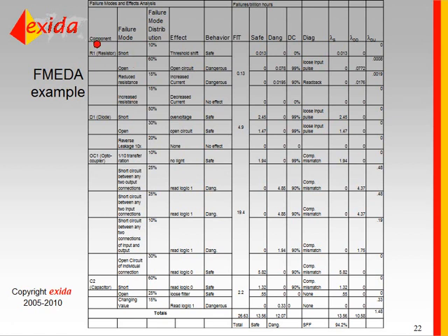So we can look at this resistor, and we know for whatever type of resistor this is that there's 4 failure modes. It can fail short, it could fail open, it could fail with a reduced resistance or an increased resistance. And this information is gotten from studies of actual field failures, for example. And those studies also can indicate what is the distribution of failures. And that tells you that 60% of the failures are open circuit, 10% are short circuit, 15% each for the change in resistance. And so there's various sources for gathering this information.